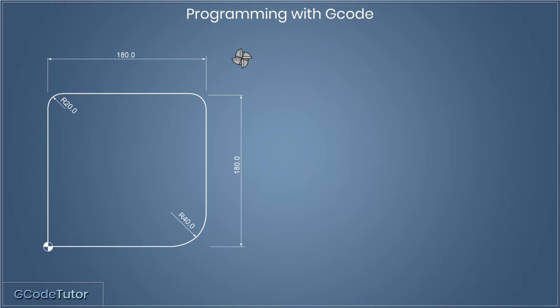Okay, so on our part, in the bottom left hand corner, we see the datum. This is where I've set the 0 position on this particular part. So x0, y0 will be on this datum, and z0 will be the top surface of the component. Now I'd like to keep z0 on the top of the component. That way, if we see any negative numbers in z, we know it's cutting and it's inside the material. So at a quick glance at the program, we can tell whether the cutter is removing material or it's above the job in a safe place.